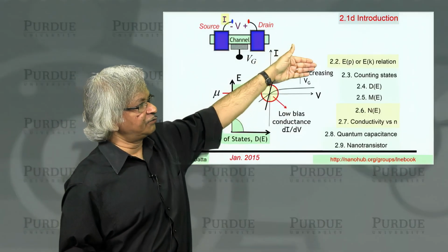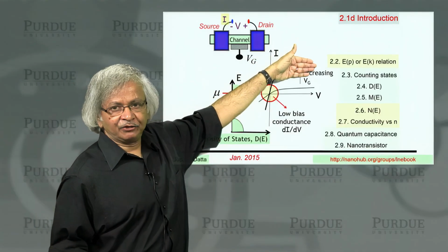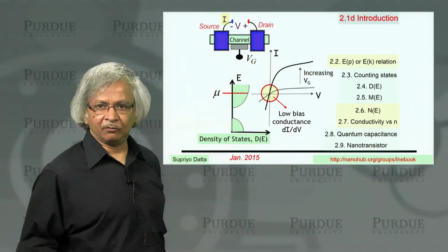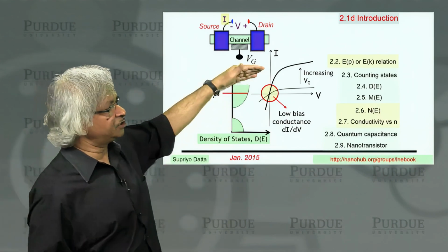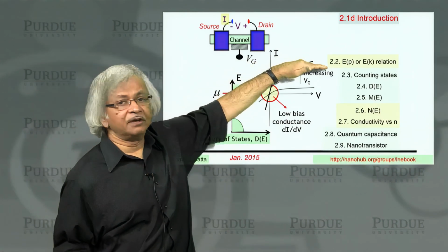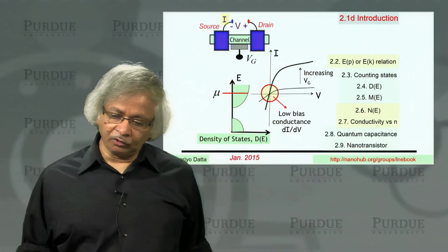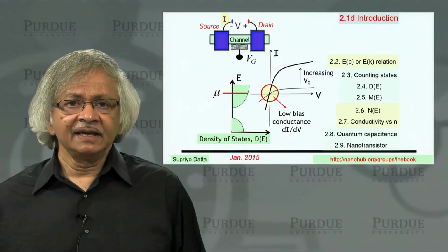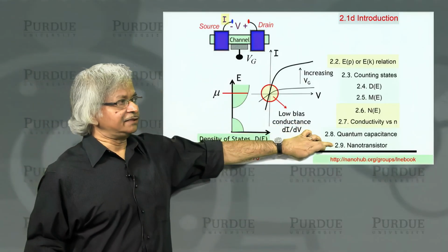That is, as you increase the voltage, the current wants to get saturated and not increase as fast anymore. That is a very important characteristic of transistors. Ideally, you'd want it to saturate perfectly. But that is proving more and more difficult to do as you go to smaller devices. And that is something we'll talk a little bit about in the last lecture.